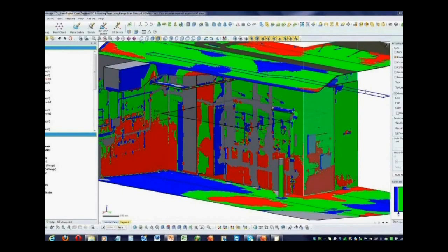There was one question left. I'm interested in generating a good triangle mesh from a point cloud or STL file, or generating a STEP file from the point cloud or STL file. Do you have this capability? Yes, of course. First of all, triangulating good quality mesh. We have several functions like the mesh buildup wizard.